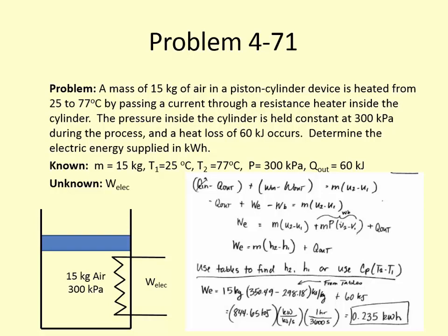Is there a work in? Electricity. Is there a work out? Boundary work. That's the tricky one. You have to be careful that there is boundary work in this problem, so there will be a work out. So we have an electrical work in and a boundary work out. Good catch, good job there, Zach. Okay, and then the mass we know. Do we know u2 and u1?